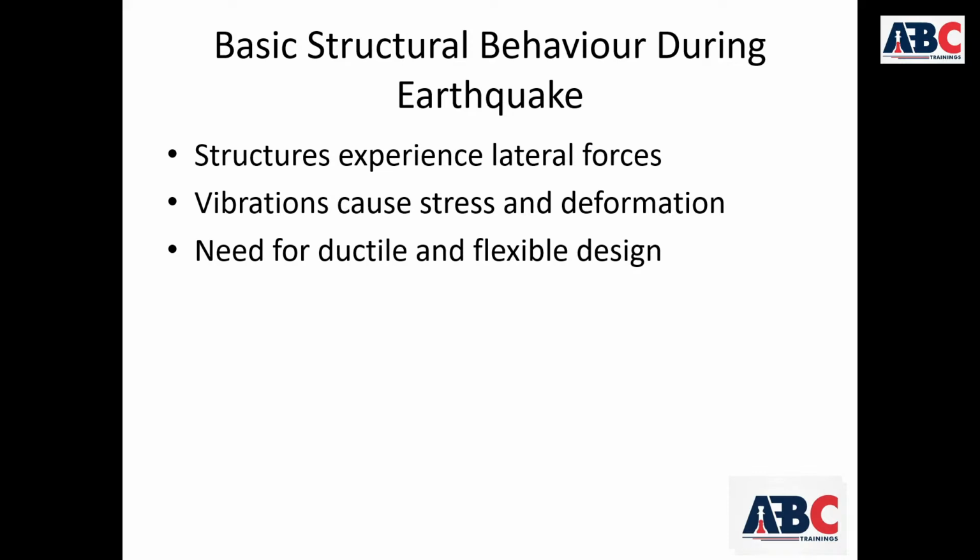This is achieved by proper reinforcement detailing, the strong column weak beam concept, and closely spaced stirrups, following IS 13920 guidelines. In simple words, we design buildings not to remain perfectly undamaged, but to remain standing after strong shaking.